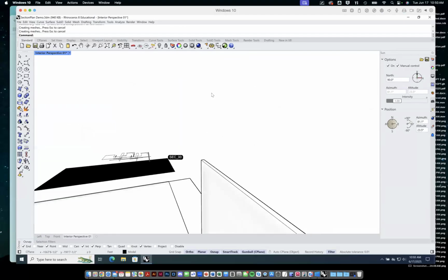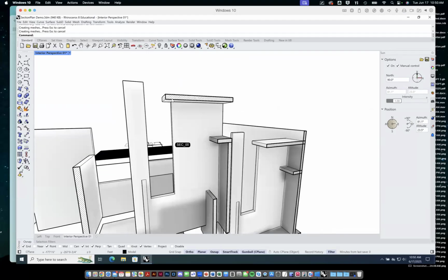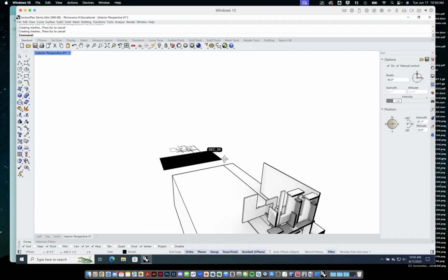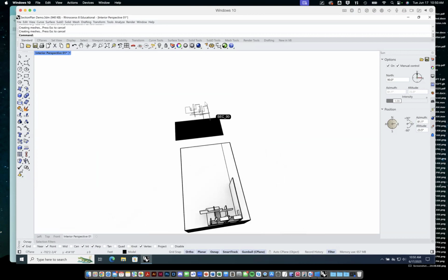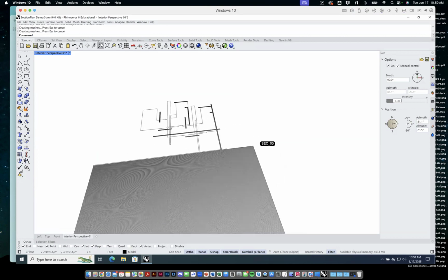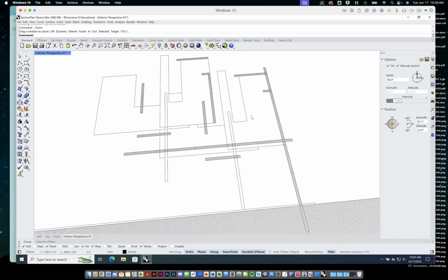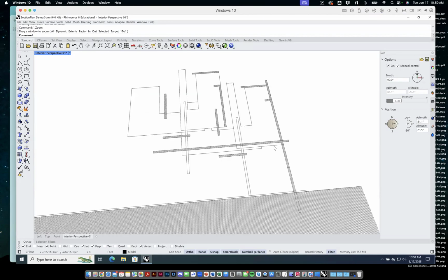And then I've made some settings to show where things are actually being cut with the hatch. I'll change that and we'll adjust those properties. We've also beefed up the line weight around the parts that are being cut, the mask, the poché. And we've turned on the sun and lighting. But we can also have this dynamic section drawing generated in 2D. So now we can see the exact same things where the building is being cut. The line weights aren't showing up here all that well, and we can see the surfaces and openings beyond, etc.